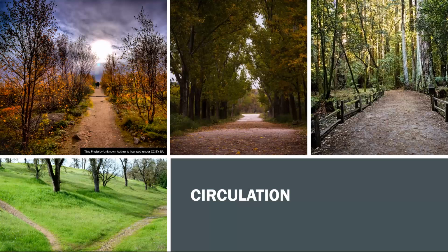You should also consider walking distances from specific destinations. And as a rule of thumb, you would typically limit or situate destinations in a way that it would only take a 5 to 10 minute walk from one destination to another, or one function to another.